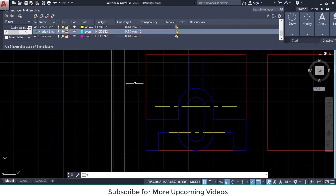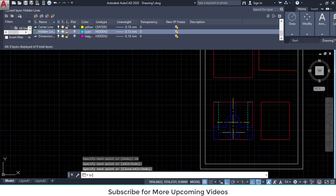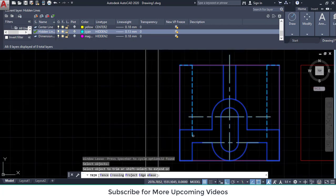So type L, then this corner 10 millimeter, and with the help of this line command 10 millimeter from this corner and draw hidden line. Trim extra portion. Trim this extra portion and trim this extra portion.